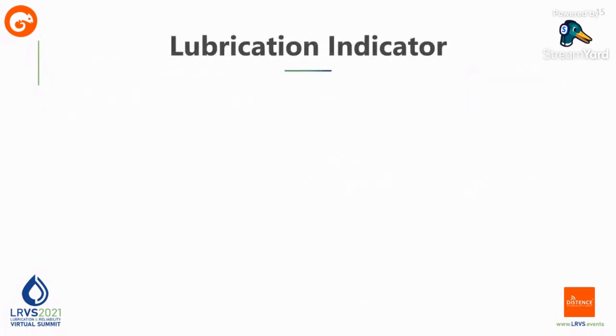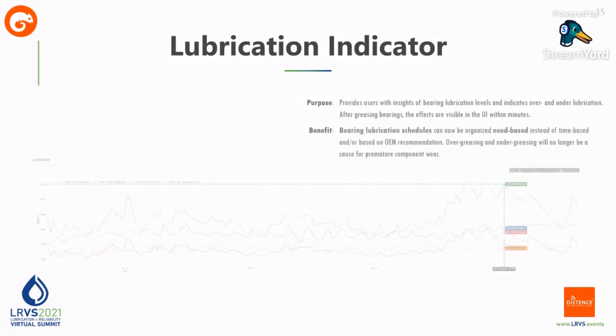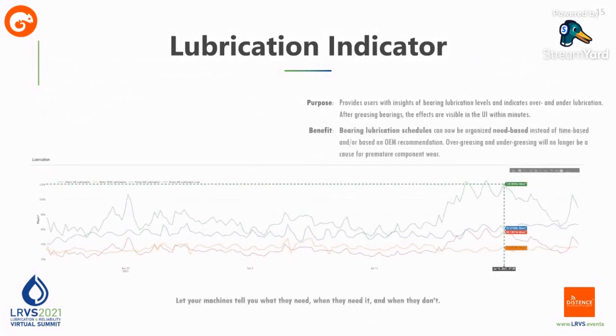Traditionally, most bearing lubrication schedules are time-based or based on OEM recommendations. Some drawbacks of these schedules are the risk of undergreasing, the risk of overgreasing, and the potential for time and resource waste, and the unnecessary environmental impact that comes with it. An alternative approach is to monitor the equipment with ultrasound technology, which is a great step away from time-based lubrication scheduling.